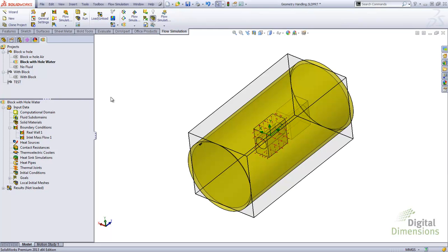Another enhancement, not really visible from the application standpoint in Flow Simulation, deals with our mesh settings. When defining a mesh control, we had a limitation of 1,000 basic cells in each direction with any of our mesh controls. In Flow Simulation 2013, we can define a finer mesh for more complex or larger models, effectively increasing our accuracy and sensitivity in our results.